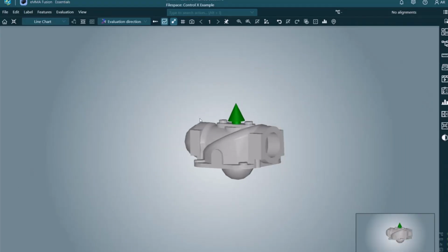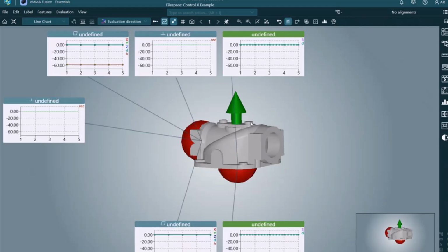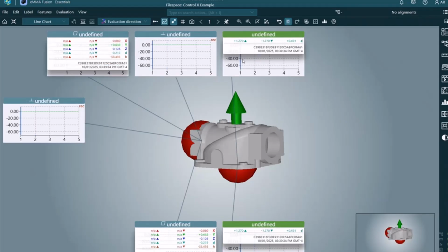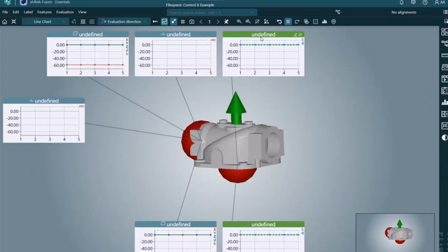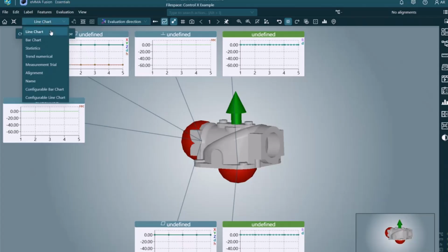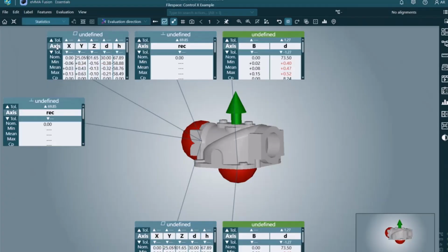Now, outside of the minor aesthetic changes we can do here, the next thing to talk about is reporting. To do a report in here, I'm going to create something called a scene. It's going to show a little movie director icon with a little plus. Essentially, if I click that plus, it's going to take a screenshot of exactly what I'm looking at. And then I can print this exact screen out as a PDF report.